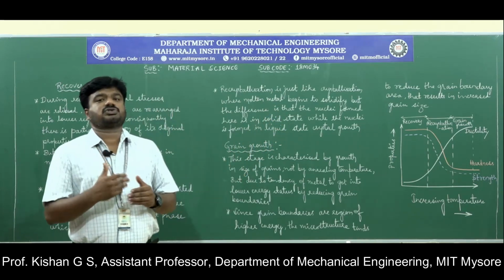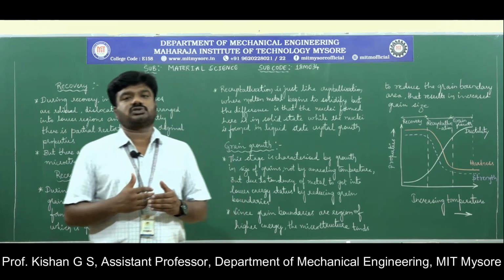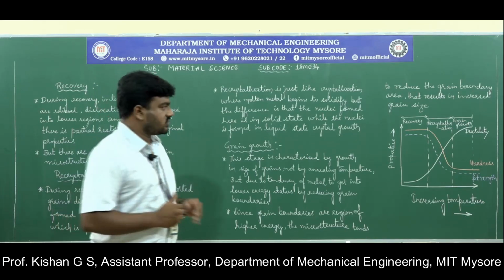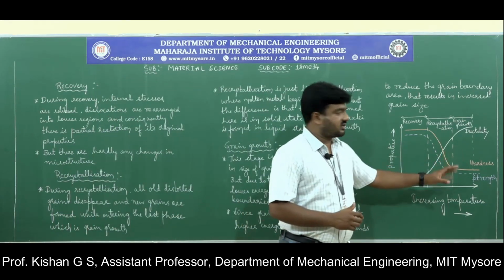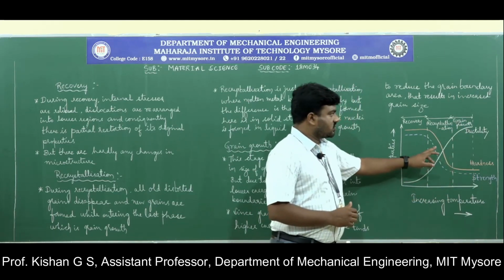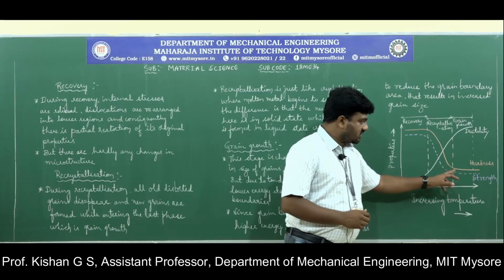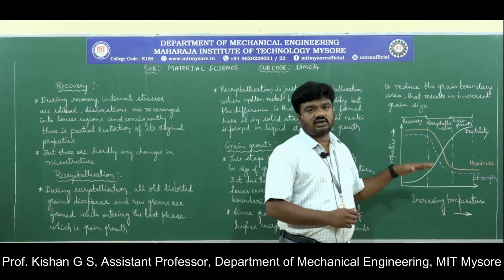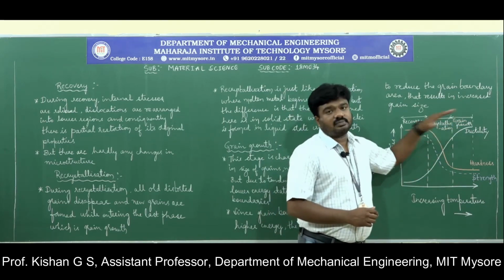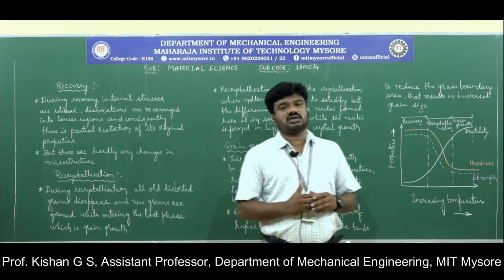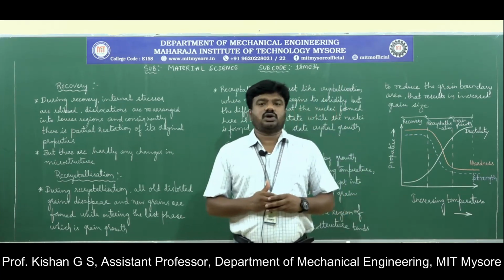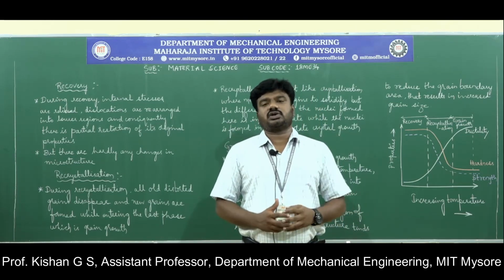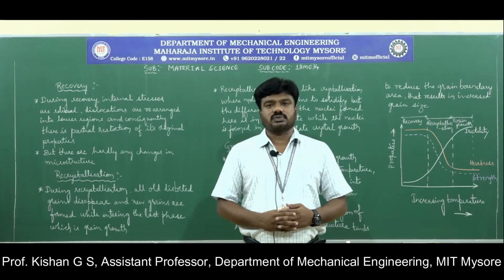It is just the proportionality, whether directly or inversely proportional, that we consider when it comes to grain growth. You can observe the same in this particular figure, the third range of consideration. In the grain growth, again the hardness and strength tend to stay at a nominal range, or tend to be constant with the increase in temperature, while the ductility goes on increasing with the increase in temperature. So this is the concept of recovery, recrystallization and grain growth with respect to the heat treatment process. Thank you.